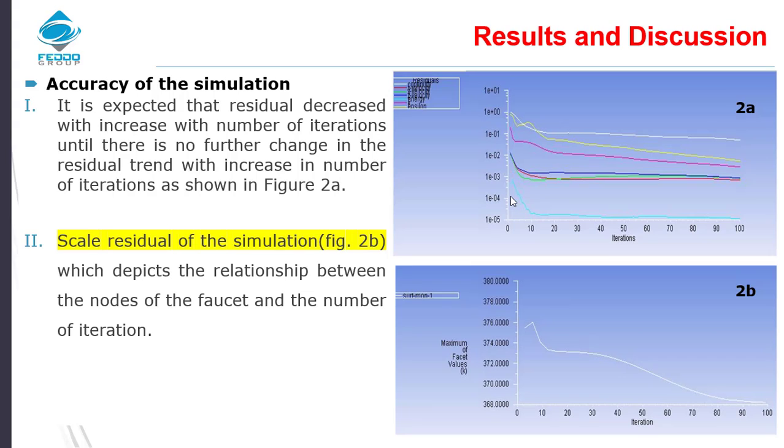So you have the consistency. Once consistency was achieved, and this was hugely dependent on the mesh, we did a lot of mesh independent study where you go back to the mesh, you readjust the mesh, then you come back here to iterate.